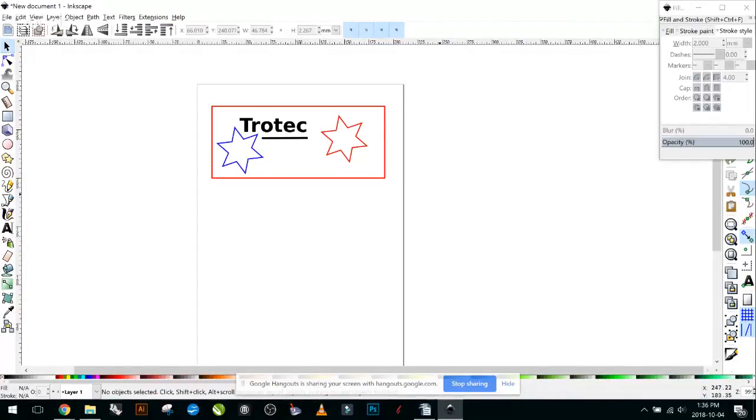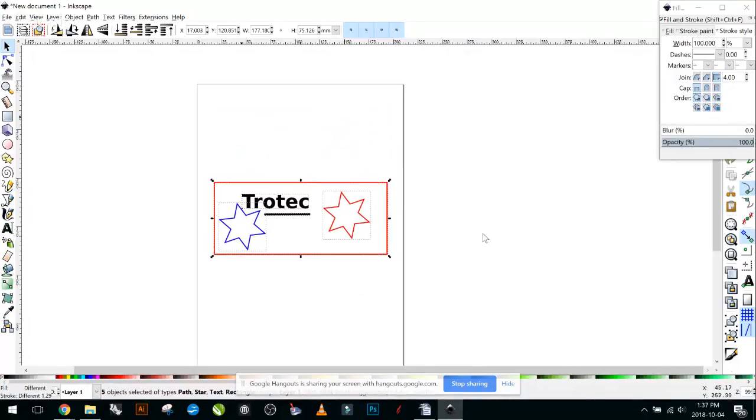But before we do that, I'm just going to show you guys there is a method that, if you do have the capabilities, we have something called the vision camera system that you can mount onto your laser. The vision camera system will find registration marks and cut out exactly where you need to be. So for instance, if you had something printed on your material, you can put some registration marks on it, and the camera will find those registration marks and cut out perfectly around that shape or picture or whatever it may be. So to do this, we'll use this as a sample.